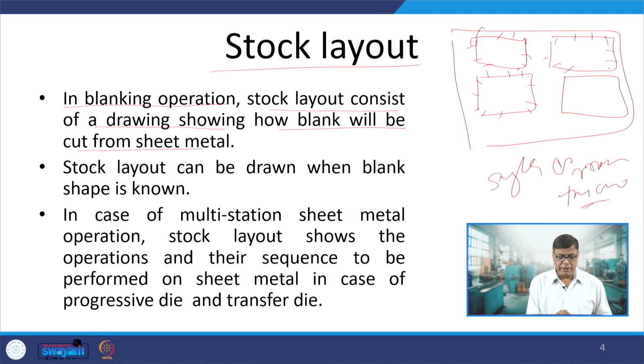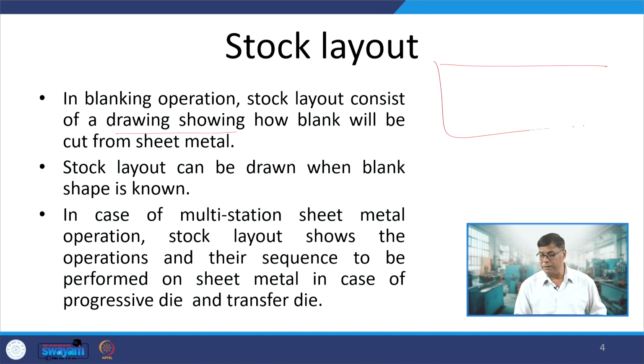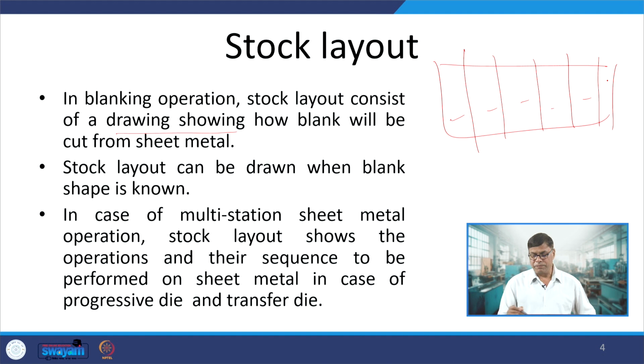Okay. So, in the blanking operation, stock layout primarily consists of the drawing showing how the blanks will be cut. If it is a simple square shape, or rectangular shape, then we will show on the sheet lines like this, from where the cut will be made, and the cut dies will be used accordingly.